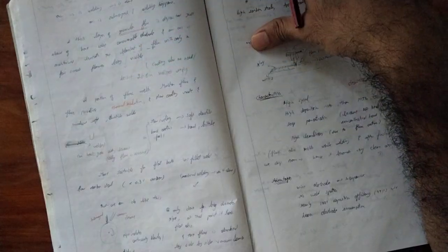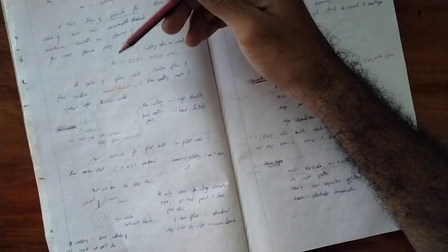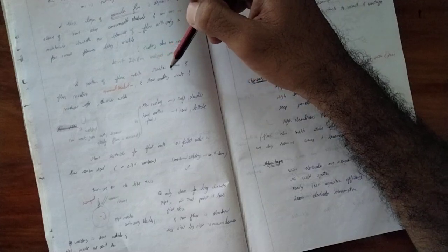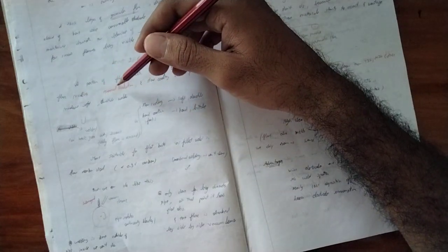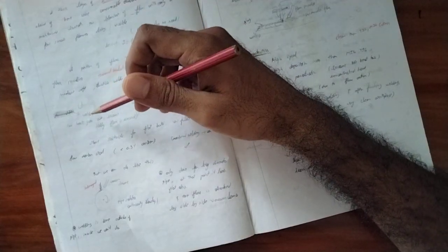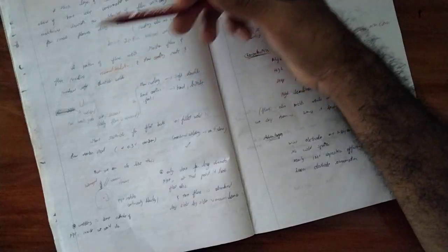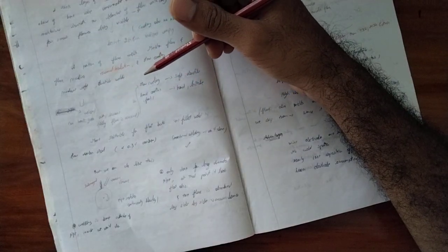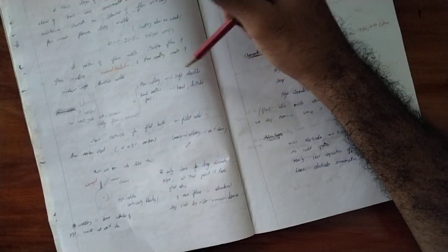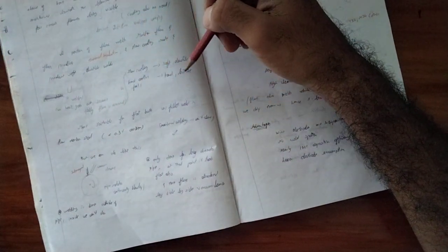A portion of the flux melts, and the molten flux provides thermal insulation. So here a slow cooling rate occurs, which produces soft and ductile welds. While we are welding, no heat goes out because the flux powder fully covers it. With slow cooling you get soft and ductile metal, but if cooling is fast, you get hard and brittle metal.